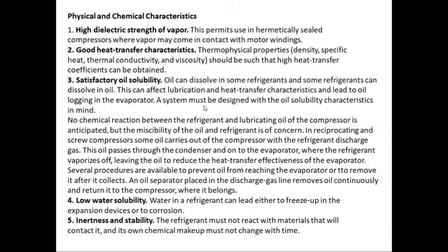That obstructs the working of the lubricant in the compressor. It cannot lubricate the piston cylinder arrangement very well, or expel heat from the casing of the hermetic compressor, because the refrigerant stays in between. So solubility in the oil is very essential from that point of view.